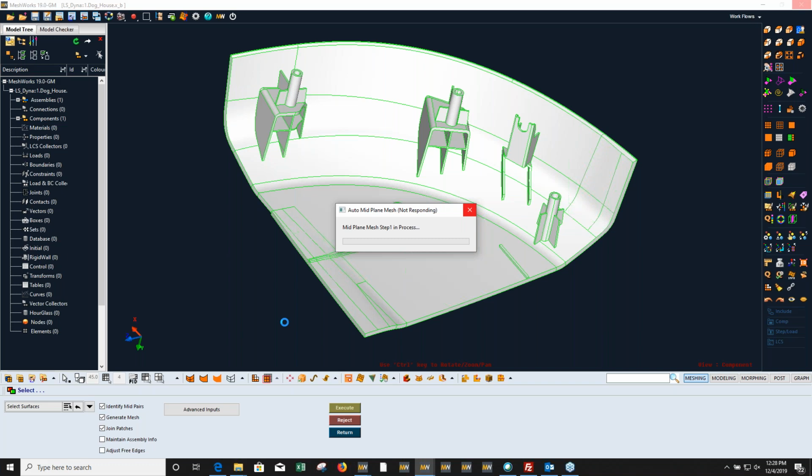And not just apply. The thing is, if you see in any other tool, we have to create the mid surface for the plastic meshing. But the good advantage of this tool is we don't have to work on the mid plane because Meshworks automatically detects the mid plane. It will create the final mesh without creating any surface. So give it another minute or so. It will complete the meshing.